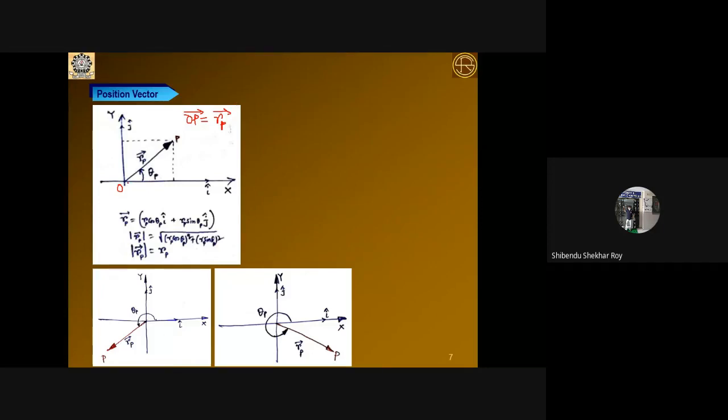In this vector, you see this is the tail and this is the head end. The vector has magnitude as well as direction. The direction is measured with respect to the positive direction of the x-axis, anti-clockwise positive. The convention I use here is that we measure the angle of the vector at the tail end, with respect to the positive direction of the x-axis or any axis parallel to x. Moving anti-clockwise, that angle is treated as a positive angle, with that value theta_P.